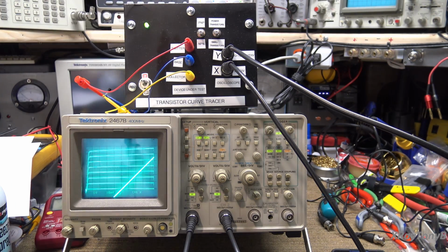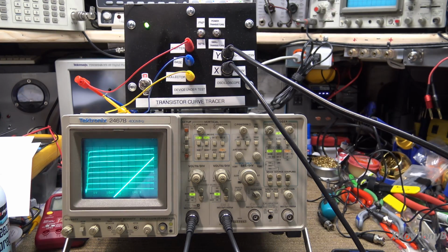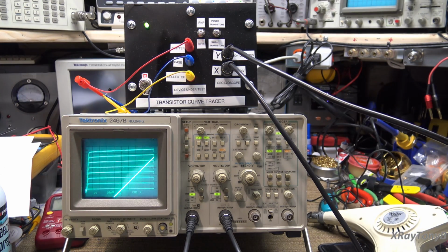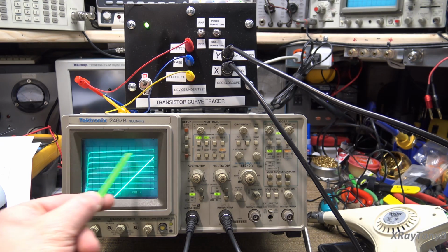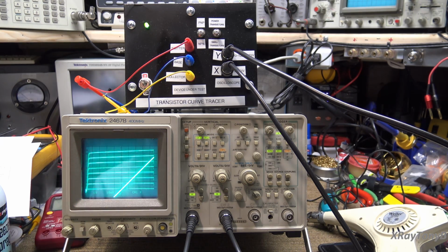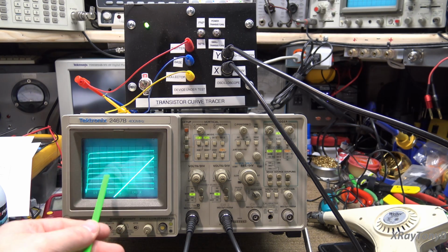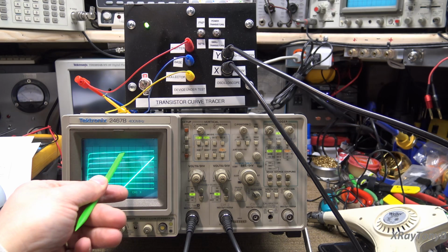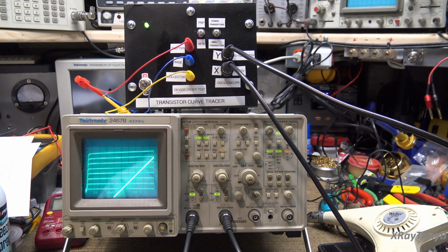Conversely, if I take the same transistor and I heat it with a heat gun, you can see the gain goes up substantially, and eventually the transistor will saturate. In addition, the early voltage gets more prominent. You can see as the thing cools back down, that early voltage, actually that slope changes a little bit. So they all interact.